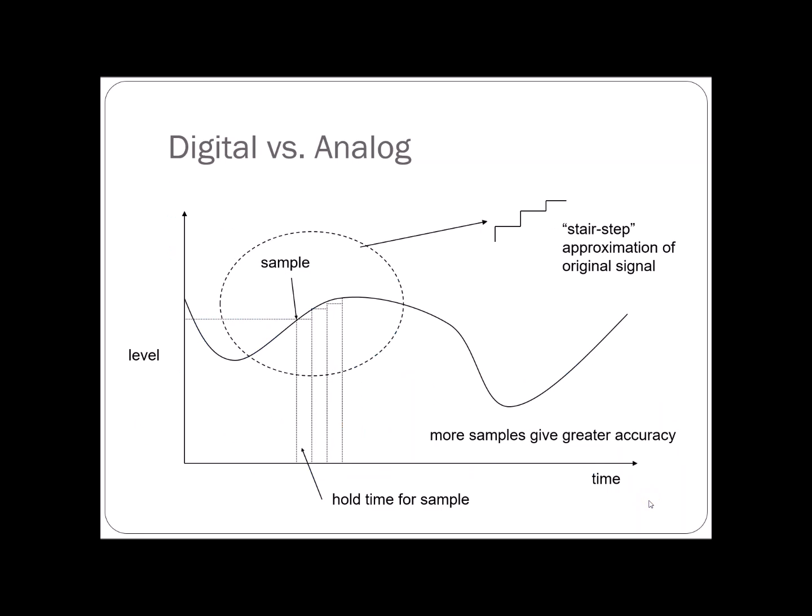Let's take a look again, a bit in detail, about this digital signal. Just an additional information that I want to share with you. Like what we have discussed before, if you have an analog signal and you digitalize it, you sample at a certain interval and then you hold the value in between of this interval, and you also discretize the y value. At the end, you will have a stair-like signal, a stair-step signal, an approximation of the original analog signal.